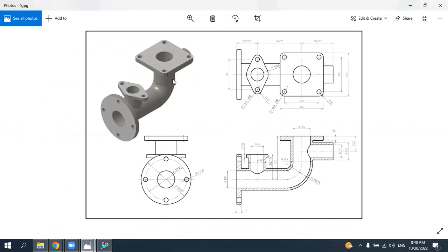We have the tube element, the solid tube element here. You can see the isometric view, the top view, the front view and the cross section view. Basically, when you create such features, a tube element, I mean a swept element, you see here that firstly you need to create the guide curve for the beginning. Then you can create this solid element either using the tube function, or the sweep, or sweep along guide. So we have three options to create this one, and you can use any of them.